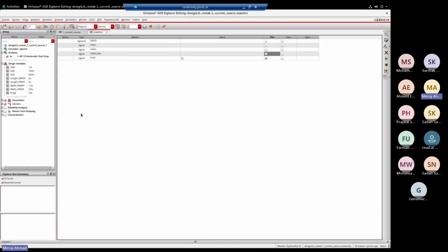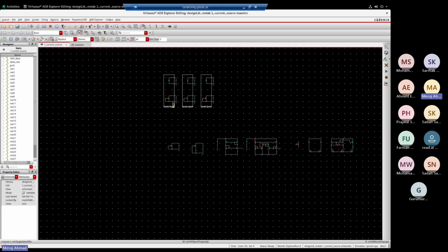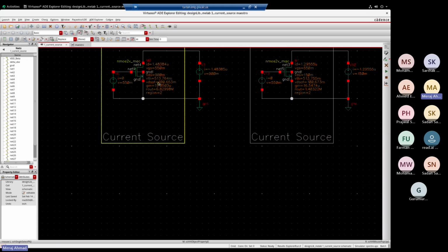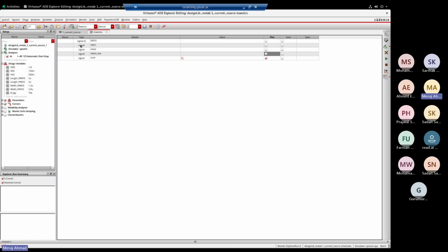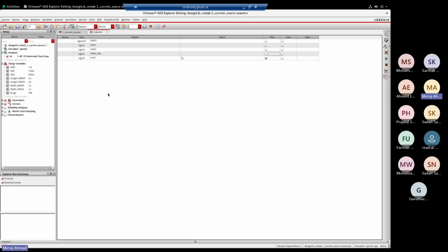Okay, so I will go here and the supply is there. I know from a very basic simulation that my VTH is around 500, so I have kept this 550. And length based on mismatch and output impedance, we go. Now suppose I make it 1 micro and 1 micro. I don't know what value of W I should keep.